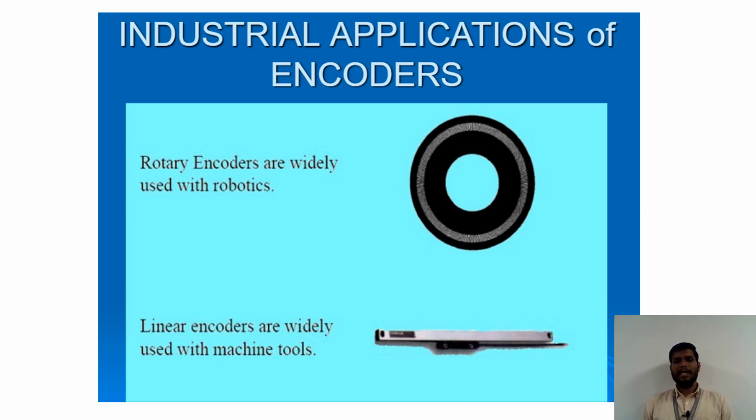The optical rotary incremental encoder consists of a glass disc with accurately etched lines at equal regular intervals on the outer periphery of the disc. The disc is connected to the lead screw either directly or through precision gearing or timing belt. The disc rotates between a light source and a photodiode. Each line makes or breaks the photoelectric beam, and the pulse signal generated is magnified to give a square wave output. A rotary encoder with 360 lines can give 360 pulses per revolution, and if a lead screw with 3.6 mm pitch is connected to such an encoder, it will give 1 pulse for every 0.01 mm linear movement of the slide.